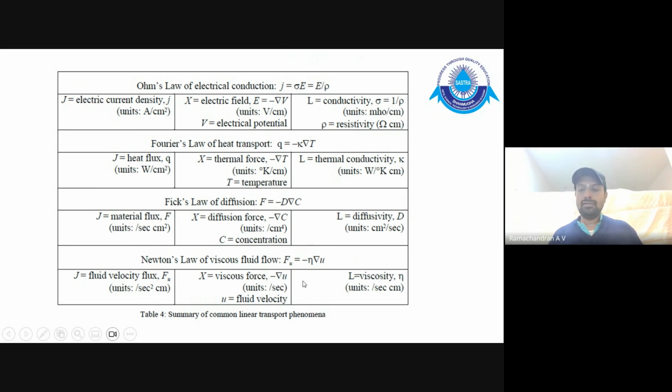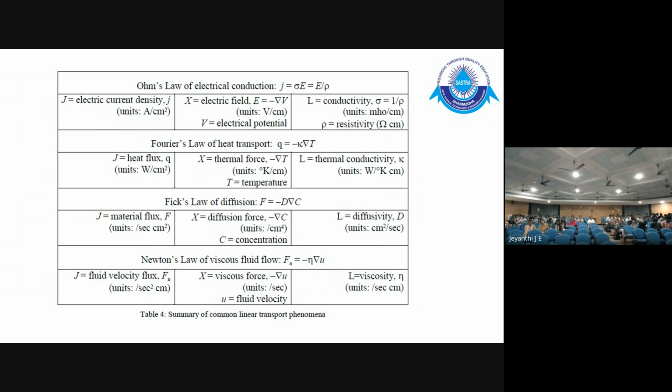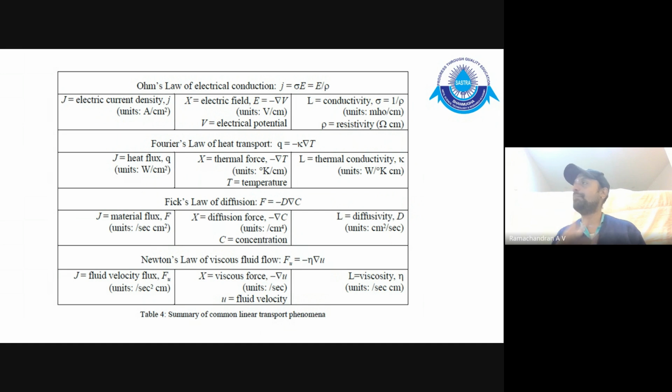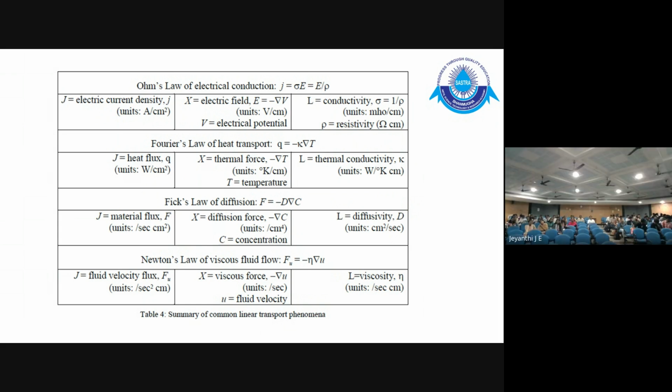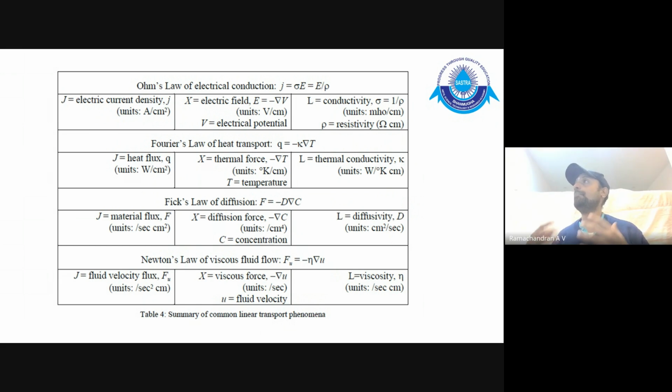Okay, so I think we can stop here. What we learned today is the very first step towards modeling. What we have seen is the dopant movement. The flux depends on the diffusion constant and the gradient, which can be written mathematically as F equal to minus D dou C by dou x. This form is prevalent not only in semiconductors, but also in mechanical and other streams as well. With that, we close here.